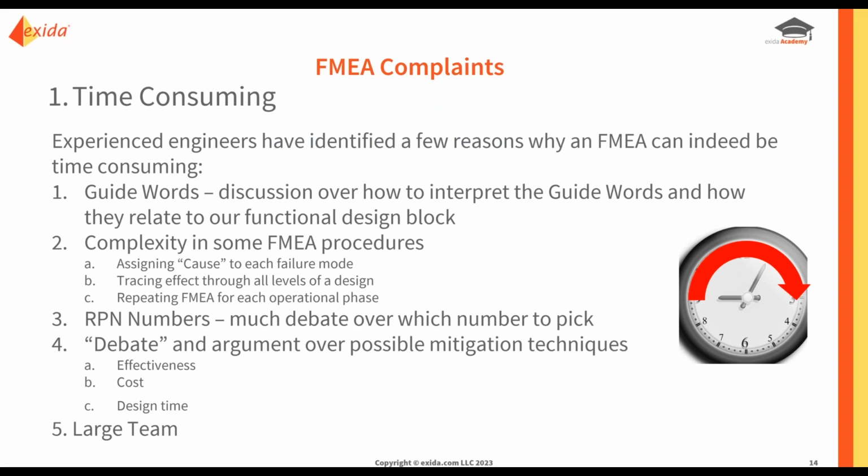Number two, many of the FMEA procedures created by companies are really quite complex. And some of the things I still recommend are, don't bother talking about the cause unless you really have to. I know why people put it down there. They're trying to justify eliminating it as a likely failure mode, but I think we should just move past that, and I'll show you some examples why.